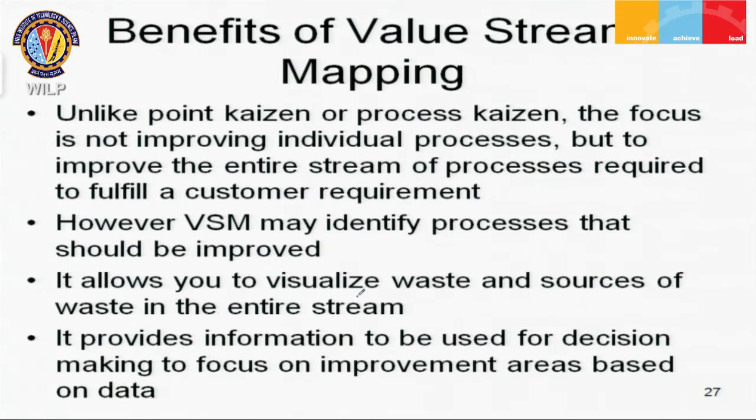However, as a result of analyzing the entire flow of the process, you may be able to identify where that flow is being held up, where there is discontinuity in the flow, and you may be able to identify individual processes that can then be further analyzed with the help of more detailed analytical techniques such as flow charts and process charts, so that those particular processes can be targeted for improvement.